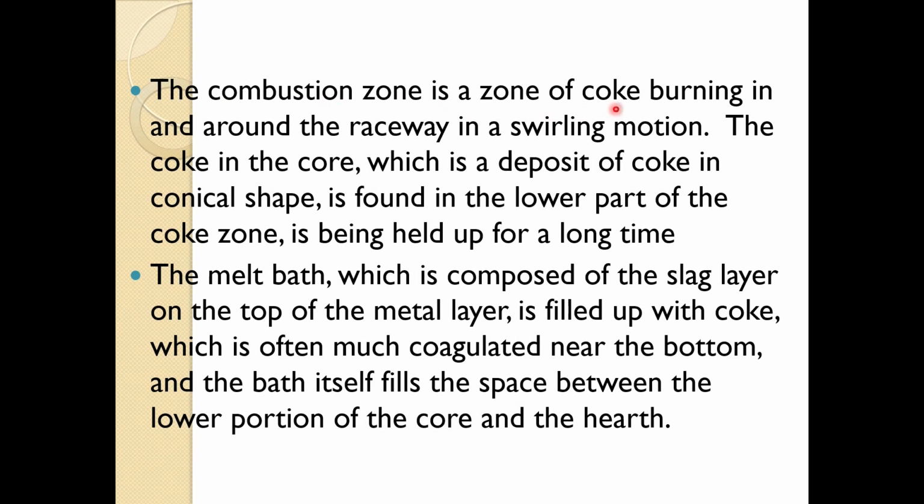So, the combustion zone is a zone of coke burning in and around the raceway in a swirling motion. The coke in the core, which is a deposit of coke in the conical shape found in the lower part of the coke zone, is held up for a long time. So, the coke in the dead man zone sits there for 14 days to 18 days or more before it is replenished or replaced by other coke. So, the residence time of the coke in the dead man is very long.